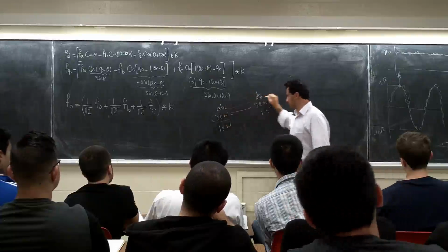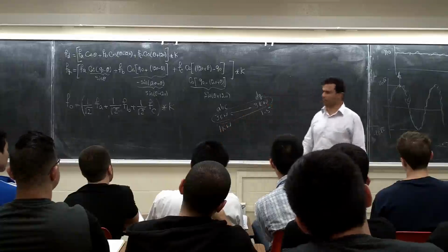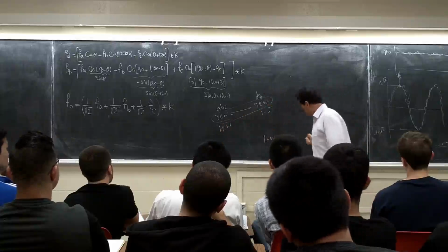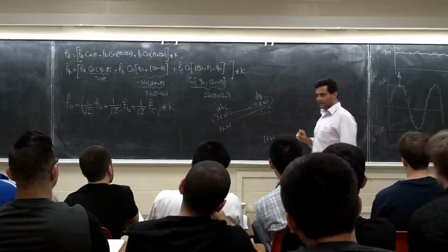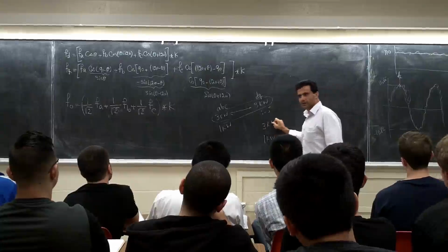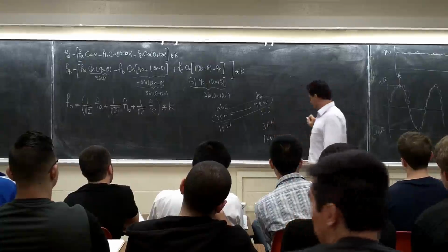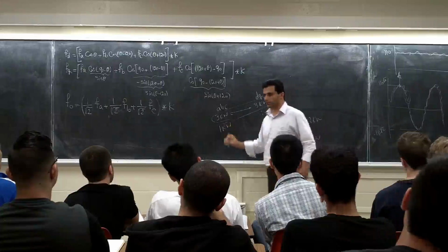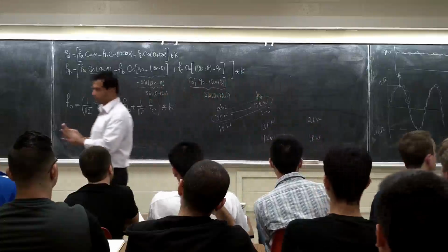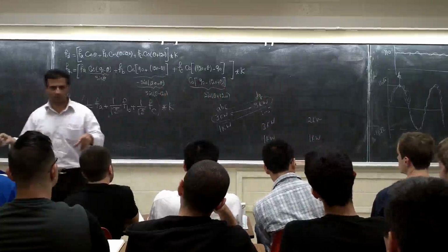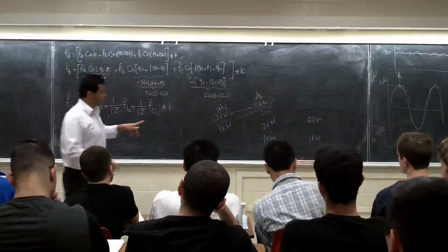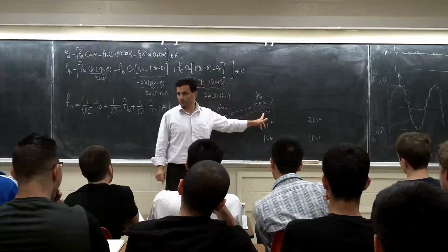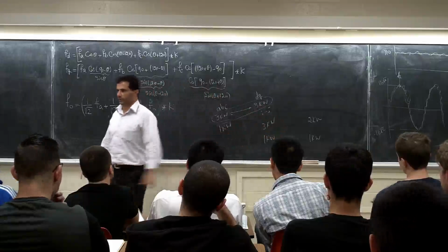Some people go with this. They say I'm going to keep my total power constant. Some people say no, I want to keep my phase power constant. They say I had 1 kilowatt here, I want to have 1 kilowatt here. So here, 3 phases, I'm going to have 3 kilowatt. Here I'm going to have 2 kilowatt. You can see there's a coefficient of 2 over 3, based on which way you go. These are all coefficients. You should correct for them at the end to make sure everything is correct. For example, if you go with this one, you should use 3 over 2 for the phase power. For that one, you should use 2 over 3. You get the same phase power.